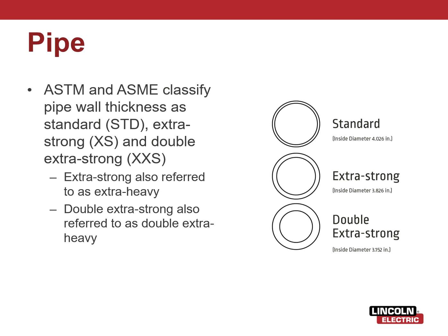So you've got your schedule, and then you also have your standard, extra strong, and double extra strong, which also changes the wall thickness. It gets a little confusing with pipe. You get a few things that start changing the ID and the wall thickness, even if it's still a 6-inch pipe. So these are just things you've got to look out for when you're looking into buying pipe.